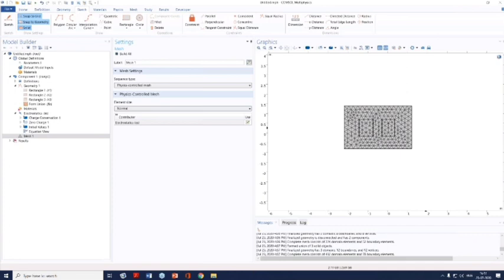And in many cases, you also want to couple these 0D models to 3D models. Again, a very basic example: a capacitor that is provided excitation through a voltage source, which is connected to a lumped resistor, and this circuit is connected to your 3D capacitor which you have designed in COMSOL.